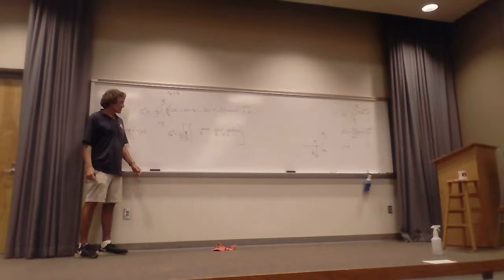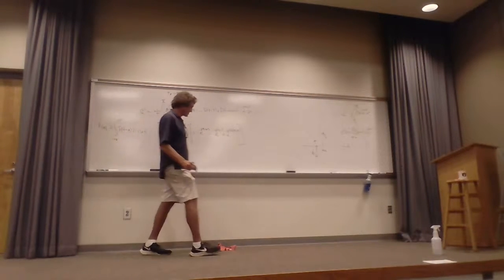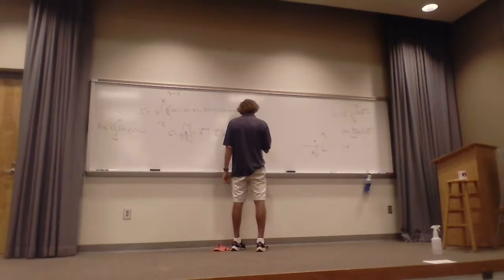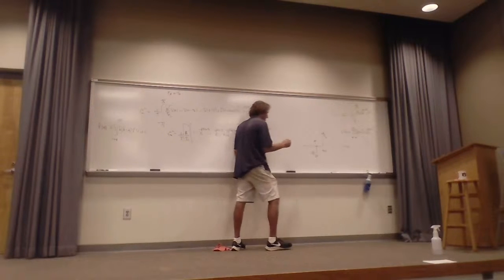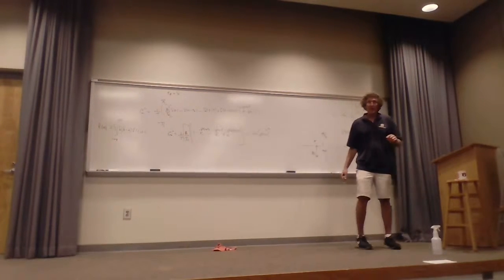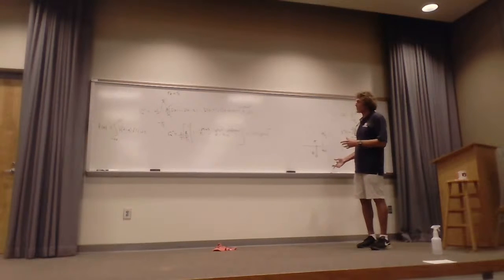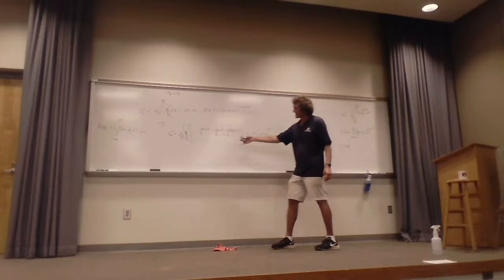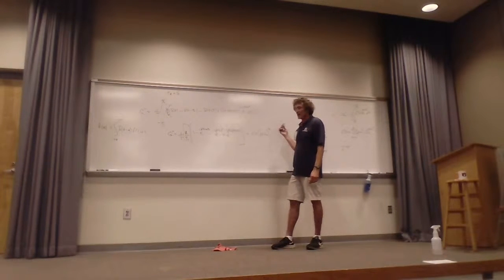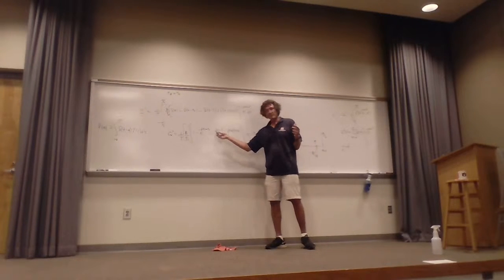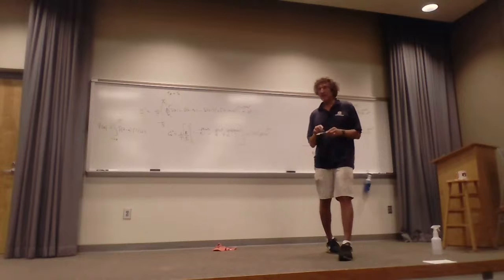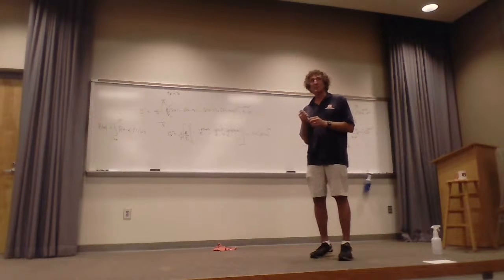And I'll just tell you what I'm going to do. I know this is equal to C of n right there times j n omega naught squared, because I took two derivatives to get there. I'm going to give you some reading over the weekend, and therefore I can get C of n just by this divided by j n omega naught. Now, in truth, let me just finish my thought here. I'm going to take this crazy expression and turn it into something that makes sense. I'm going to turn it into a couple of sines, multiply them by each other, and divide by some arguments that will eventually render them as just sinc functions.